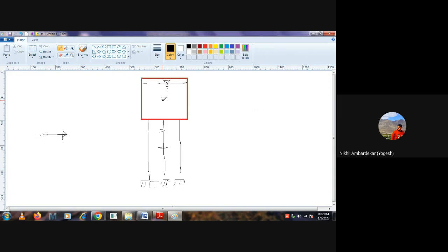Center of gravity. Okay. Yes, sir. So we need to apply this force to the center of gravity. But what are we assuming? First, we have calculated the entire weight of this structure with different elements: empty container plus staging. Because of that, the CG will be somewhere here, and as compared to that, what does the code suggest?